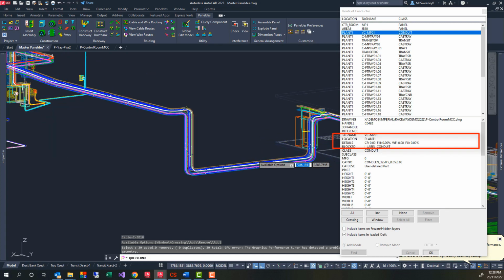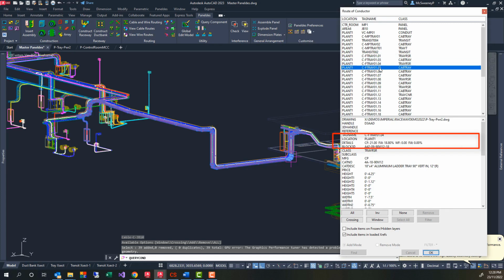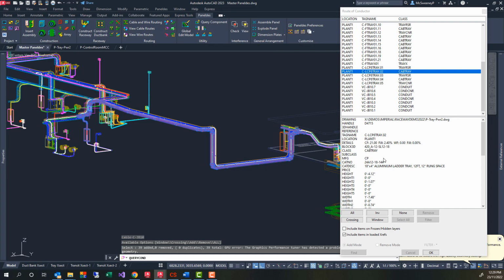When a cable appears to be going the wrong way or not finding a route, we provide a diagnostic system called the bottleneck system. The bottleneck system allows a cable to pass through bottleneck trays. Bottleneck trays are constricted, undersized, badly connected, or have an inappropriate voltage level. Whenever a bottleneck tray is used in a route, the query tool marks that tray. If the routing system produces a shorter or more desirable route using bottleneck trays, then those trays are probably undersized or badly positioned. You can simply increase the size or position of the bottleneck segments to ensure the cable takes the best route.